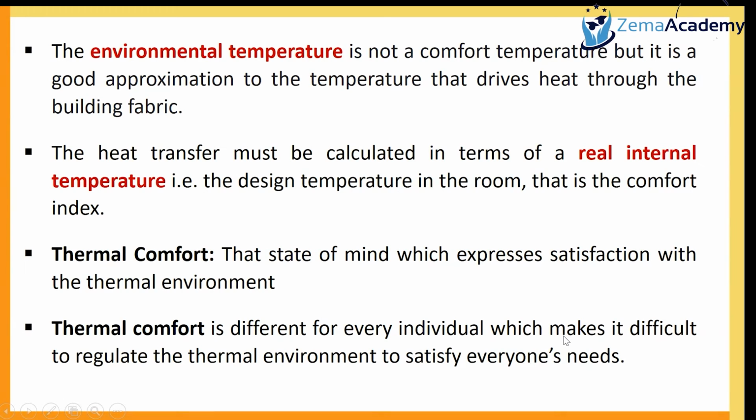Before that, just a little information. When we did all this derivation and came up with the new equation which included environmental temperature, I pointed out in week 2 also that this environmental temperature is not a physical temperature. It's not a real temperature. It is a temperature that has come up because of the linearization of the heat transfer term and accommodating the radiative heat transfer term.